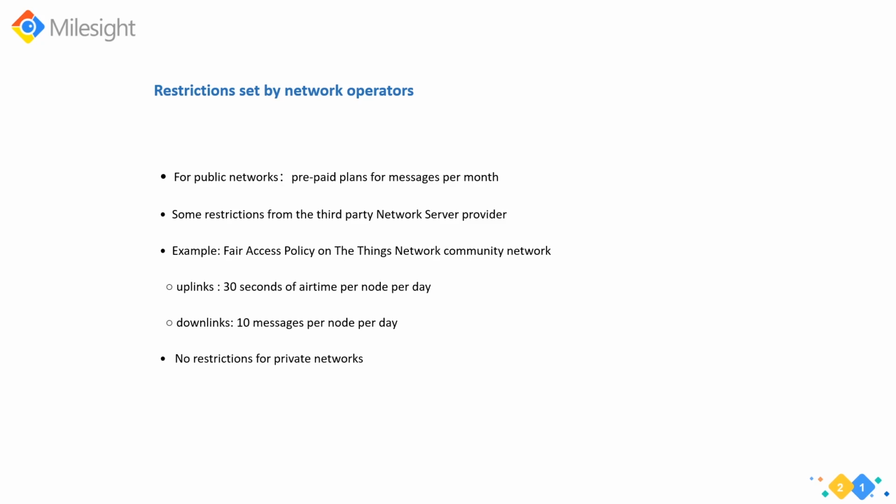So you don't need to use any third-party services to build up your own private LoRaWAN network. Then in that case, you don't need to respect those restrictions. But you still need to respect the duty cycle and the dwell time.